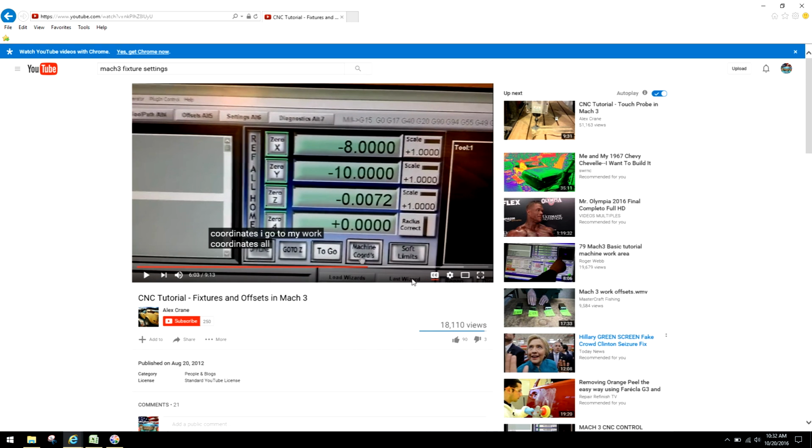Okay, guys. Point of confusion. Machine coordinates are telling you basically where on the table you are, looking at where your spindle is. Okay? That's all it is. When you go to your actual work coordinates, where you want to go to where your work is, that's where the fixture came up, and that's why it's reflecting -8 and -10 on his X and Y. Okay? So once again, arbitrarily, machine coordinates means basically if you want to know, oh, look, my spindle's hanging 2 inches off on the X and Y, whatever that means, if that means something to you.